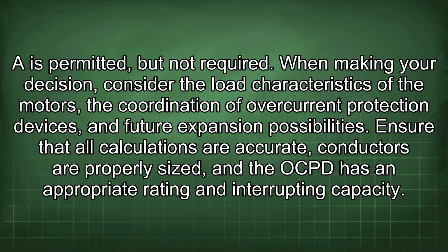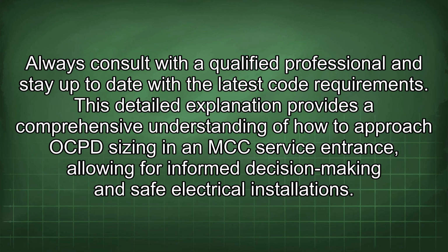When making your decision, consider the load characteristics of the motors, the coordination of overcurrent protection devices, and future expansion possibilities. Ensure that all calculations are accurate, conductors are properly sized, and the OCPD has an appropriate rating and interrupting capacity. Always consult with a qualified professional and stay up to date with the latest code requirements. This detailed explanation provides a comprehensive understanding of how to approach OCPD sizing in an MCC service entrance, allowing for informed decision-making and safe electrical installations.